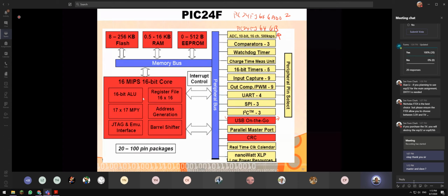So when you come to OTG, it's just like a handphone. Your handphone is a bit different. A handphone can be a peripheral and can be an OTG. So if you want OTG, you need a special cable, correct? So basically, if you talk about OTG, there's one additional pin on your micro USB socket. Okay, but of course, your microcontroller must have that feature to support OTG.